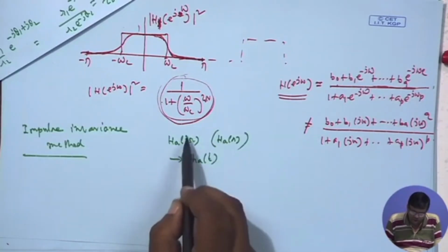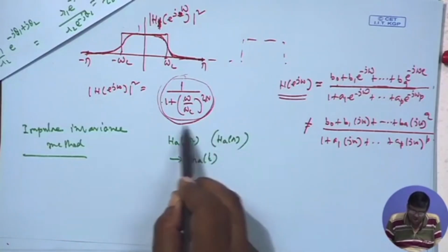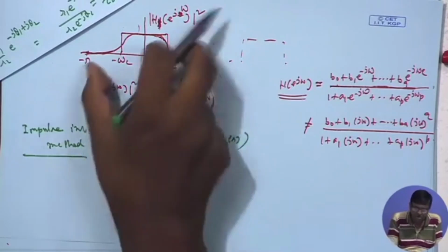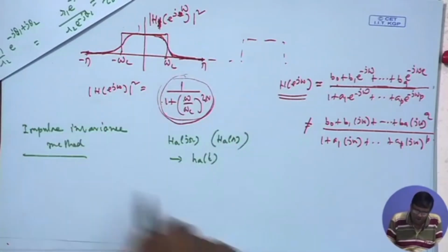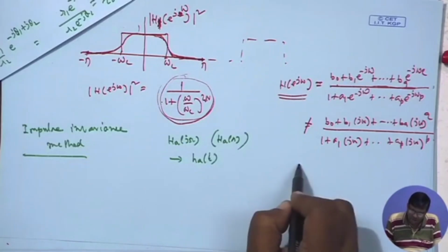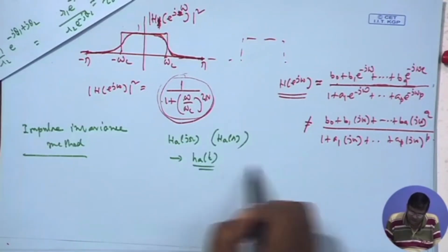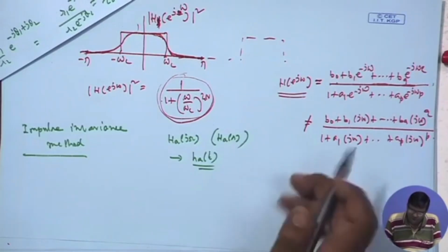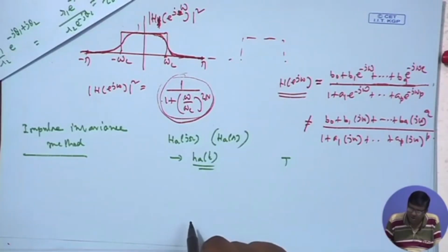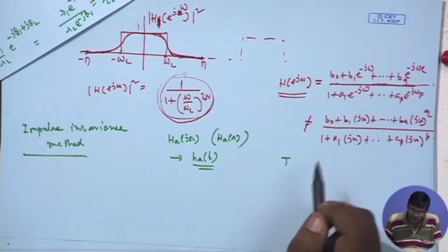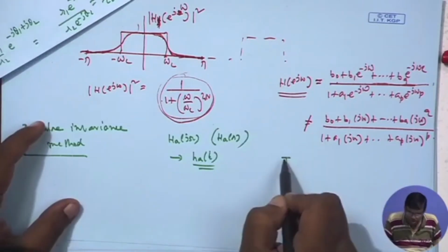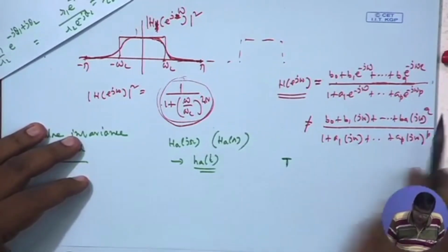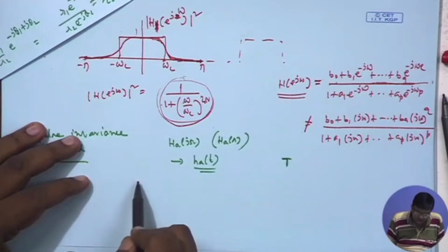We assume there is one such H A(j omega) which is band limited, also Butterworth band limited, going down to 0 like this, and we sample this H A(t) at the Nyquist rate or above. So we choose a sampling period capital T.